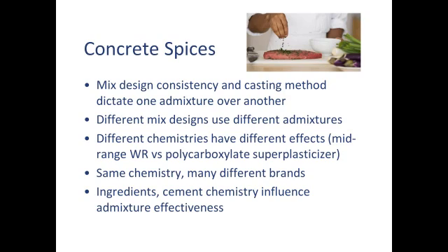one admixture over another, a water reducer versus a super plasticizer. Different mix designs use different admixtures. If I'm pouring a driveway, and that driveway is on a hill, and I want to just add a little bit of slump to my mix and still make a good mix, I'm probably going to be using a low or mid-range water reducer. On the other hand, if I'm pouring a very intricate wall that has undercuts and details in it and I want a high-quality casting, I'm going to be using a very powerful superplasticizer. Same kind of admixture, but a different chemistry.